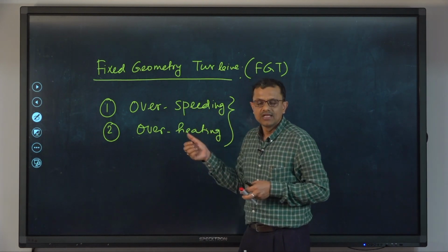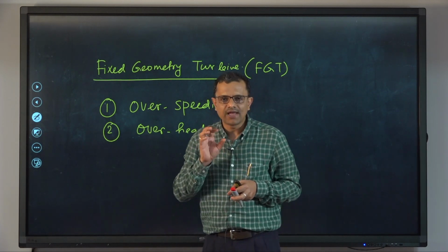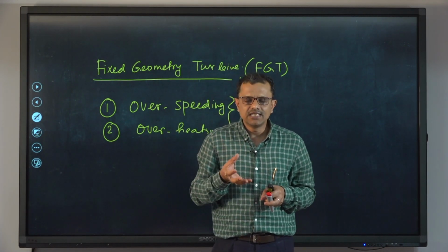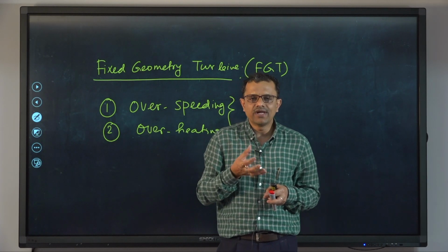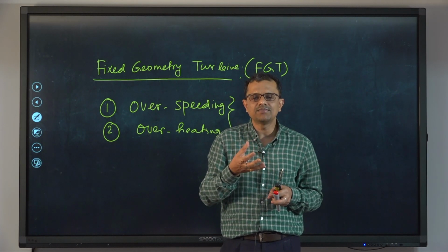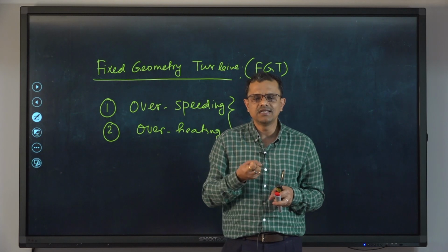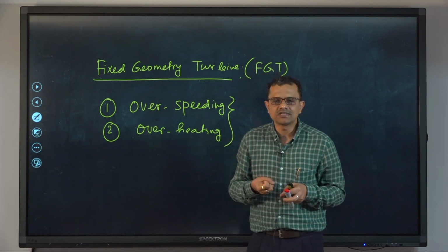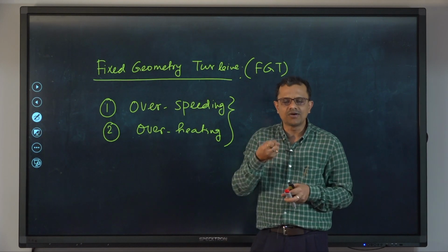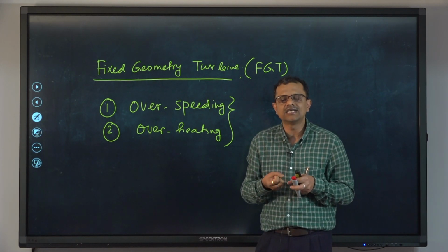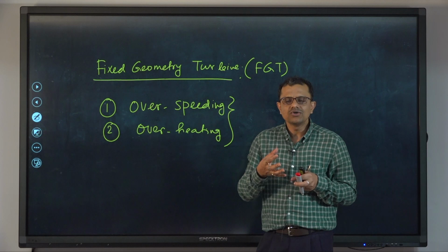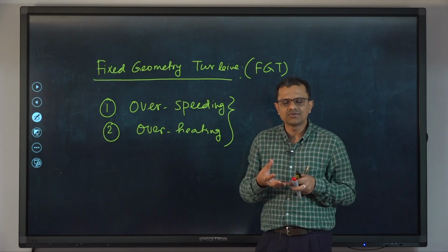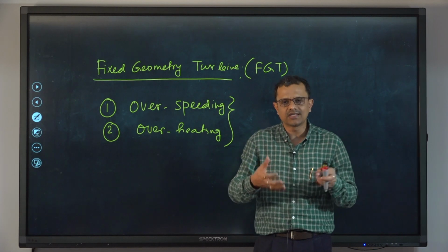What is overheating? The sole purpose of having this unit, whether it is a supercharger or turbocharger, is to increase the inlet pressure. When the intake air is compressed, the pressure of the charge will be further compressed inside the cylinder during the compression stroke. So, the pressure will be even higher at the end of the compression stroke, which is accompanied by higher temperature as well.